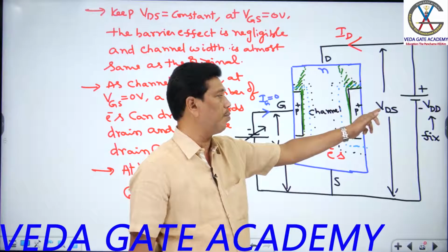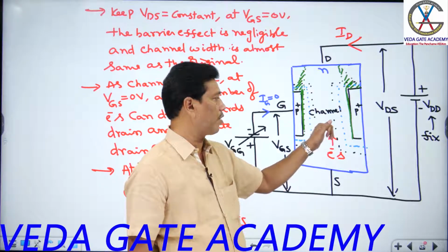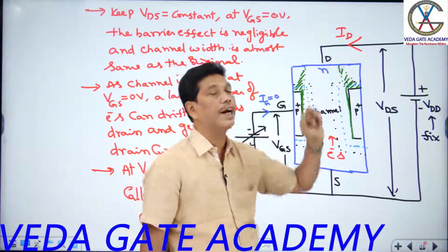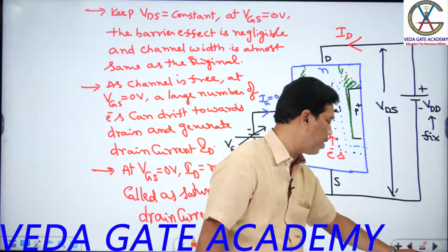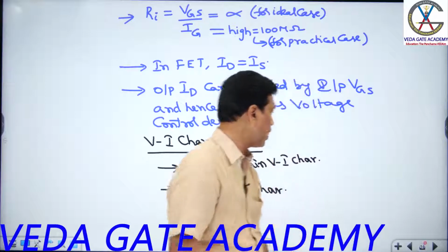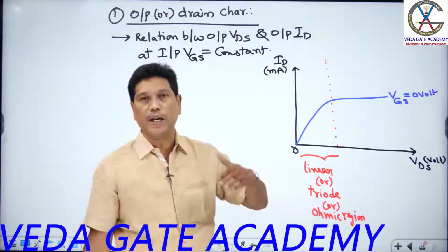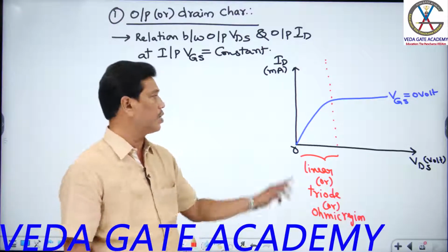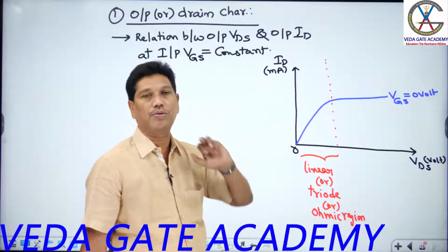So with the increase of VDS under the low voltage region, the flow of electrons increases in linear mode, and thereby the drain current increases linearly, students. Increasing the drain potential under the low voltage region means the repulsive force acting on the electrons also increases linearly, such that the current increases linearly, and the current rises like this.